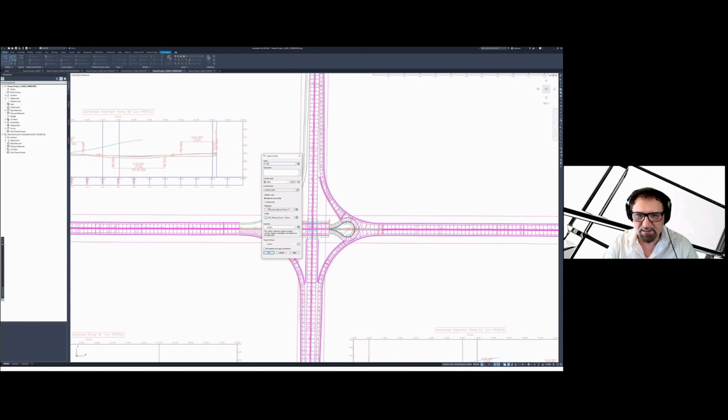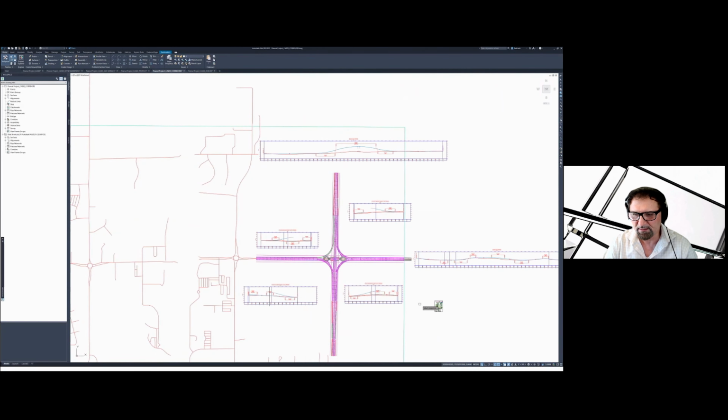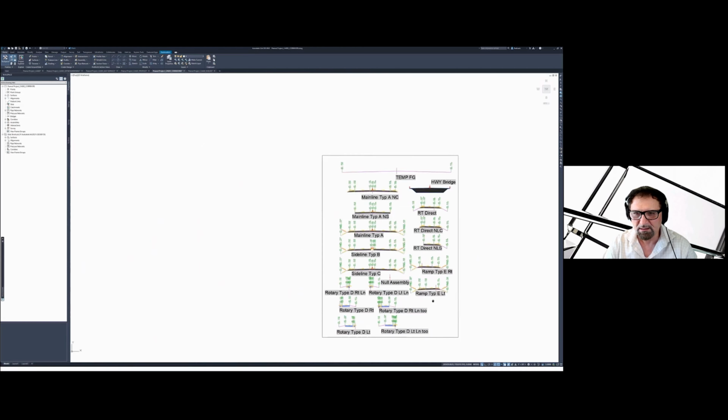So I'm going to select the alignment now, even without knowing exact alignment name. I'm just going to select that from the screen there and use the layout profile right there. That's the one that we designed. And the starting assembly is going to be from my library. I'm going to go and select it from the drawing. And here they are.